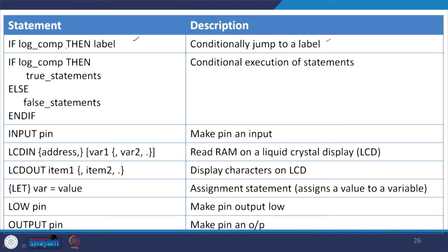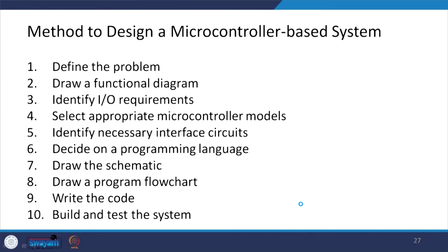So, if log comp, then label, something like this. Okay. And conditional execution of statement, that is if and else type of statement. Okay. And it terminates with the end if statement, and input pin, making a pin an input, low pin, make pin output low, output pin, making pin an output, and so on. So, likewise there are many more commands which I have not discussed over here. As I said, you can refer to some standard textbook or PIC 16F84 catalog to know more about the programs.